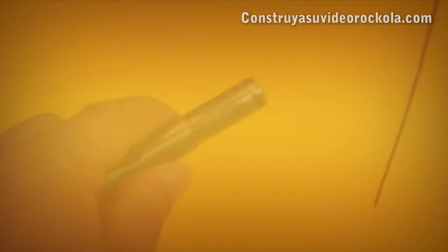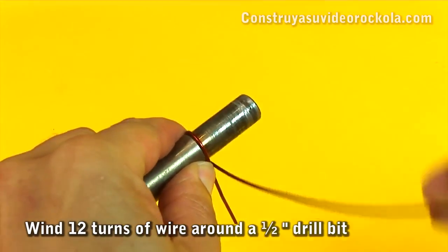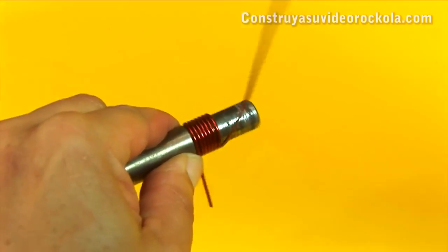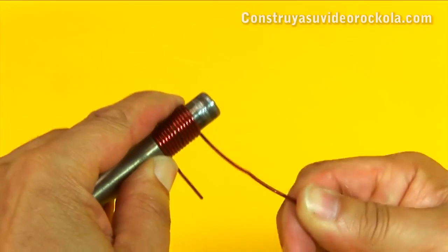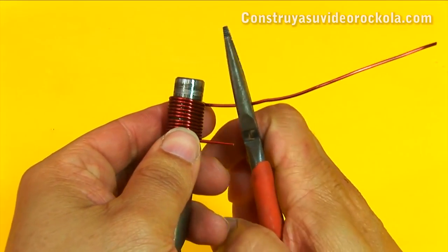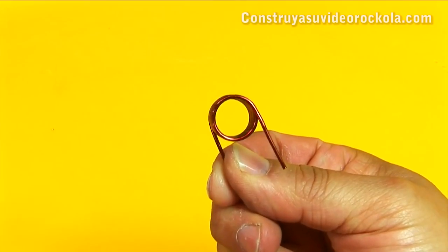Assembly. We will begin by making the coils. We take enameled copper wire, and wind it around a 1/2 inch drill bit. We roll up 12 turns. They must be well aligned, and without spaces between one turn and another. We cut the excess wire. The coil should be as perfect as possible.